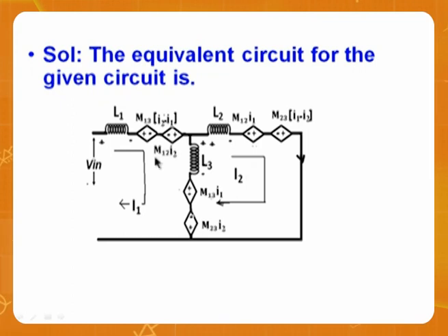So when we have this coupling, whatever the value here, the same value comes there, but the only difference is this is due to I1, whereas this is due to I2. Because on the first coil, the second one has to induce. On the second coil, the first one has to induce. So I1 induces here, but the polarity is with respect to I2. So see there, plus minus, we already said minus plus. So M12 is opposite, therefore here also opposite, plus minus, minus plus.